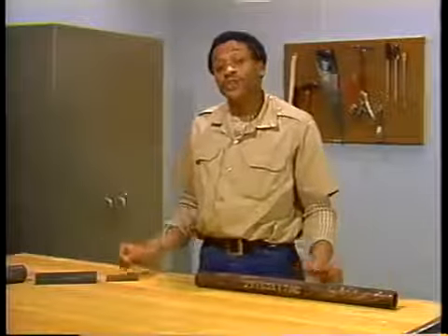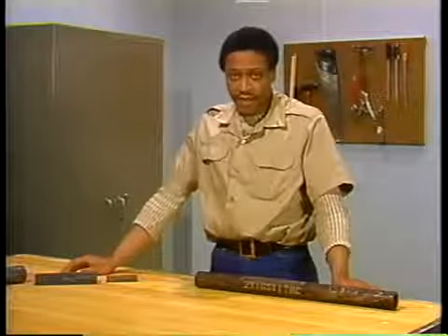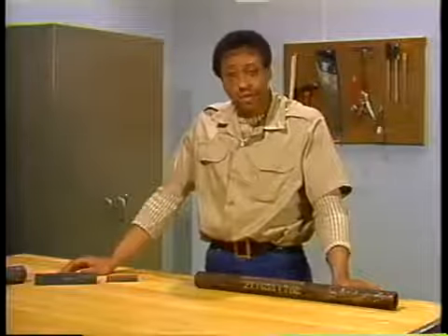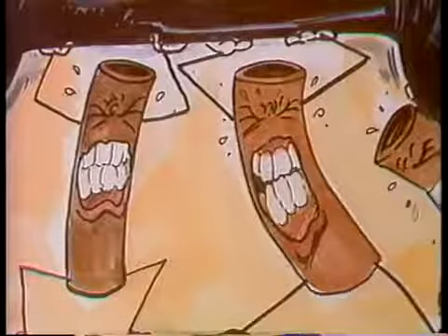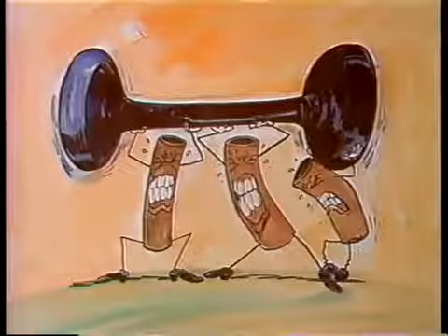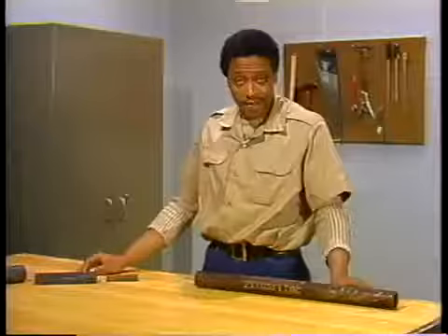Mechanical stress is also created by weight. Boiler tubes must support their own weight plus the weight of their contents. In boilers that hold a lot of water, this weight puts a heavy mechanical stress on the tubes. The tubes are designed to withstand this stress, but if they're weakened by overheating, corrosion, or erosion, they may not be able to handle it.